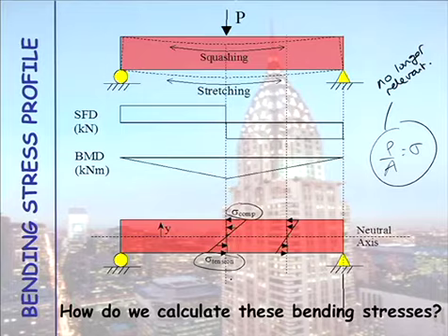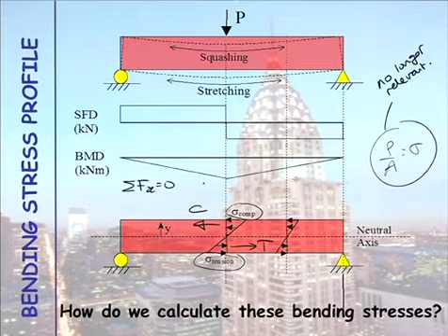So you get this linear stress distribution. From this stress distribution at the top, I have a net force to the left, I call it C. And from the bottom, I have a net force to the right, T. Because of equilibrium, those two forces have to add up to 0. So they are equal and opposite. And those two forces as drawn, can you see they create a couple? That's what causes the moment in the beam.